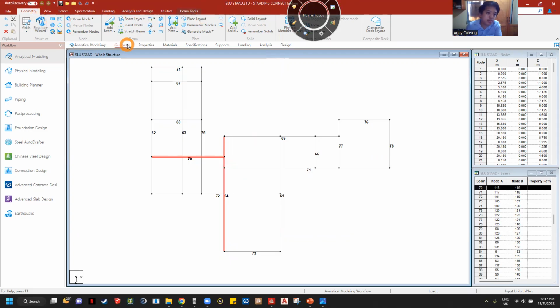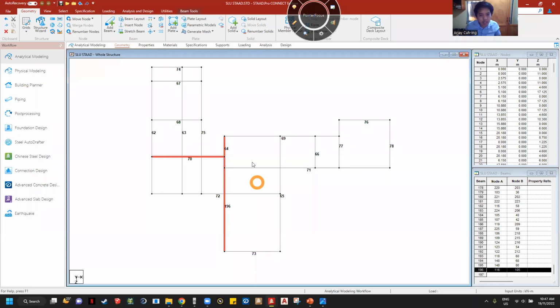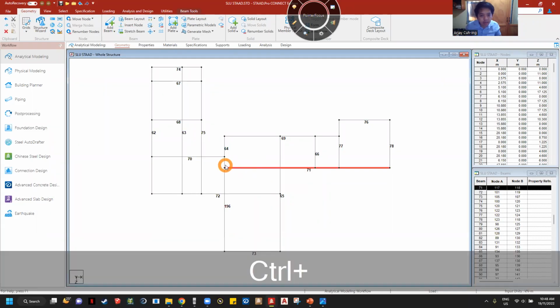So how will we do it? So go for the first path. Technically, meron tayo dito, no? Geometry menu. As we go here, that one, and then intersect beams. Tapos we enter a tolerance number of 0.001. That's the one in default. Just press OK. So you can see class, beam number will be created here. Yan. Okay. So as you can see, supposedly, this one will have 3 beams na. 1, 2, and then 3. Gets ba?